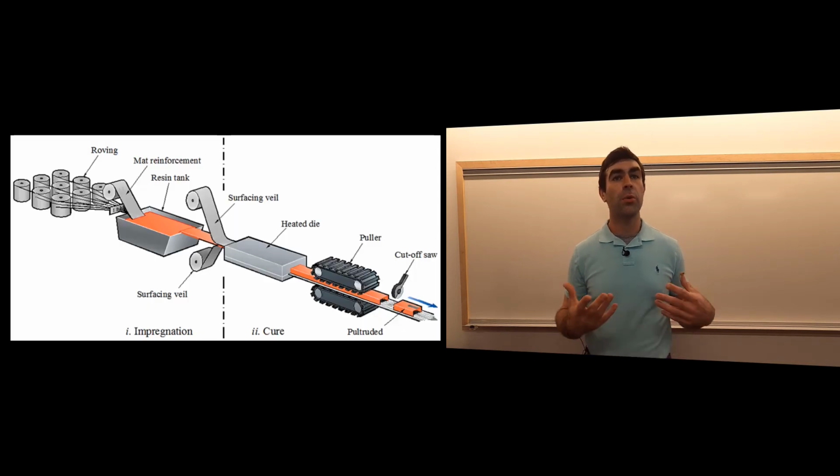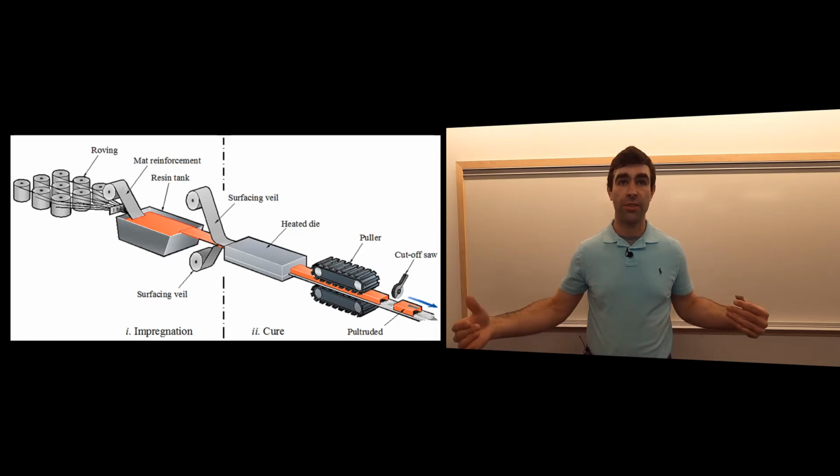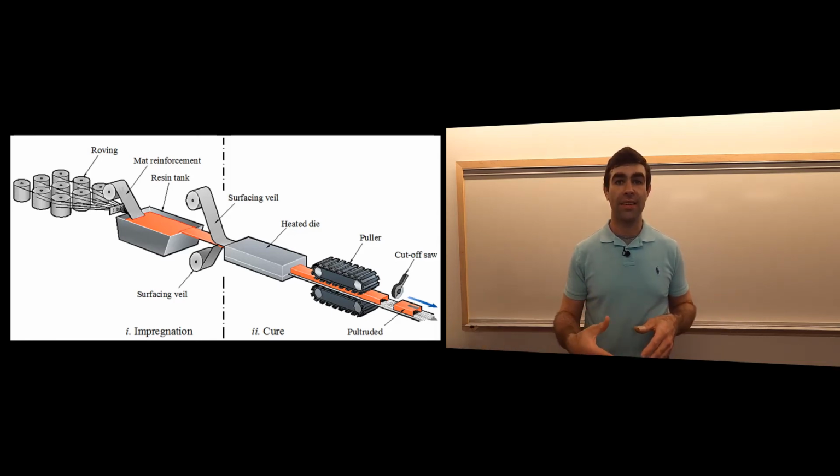In pultrusion, it's a similar process but more complicated, because what we're doing is adding continuous fiberglass fibers into that plastic. So this makes it very, very strong, but a lot more complicated because you have to twist that fiber and get it through the extruder with the plastic and the right heat all at the same time.